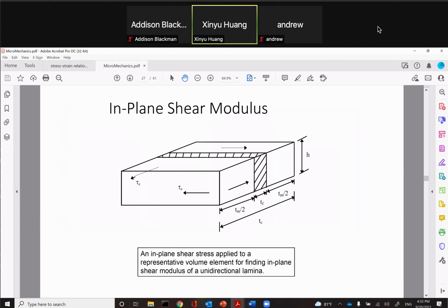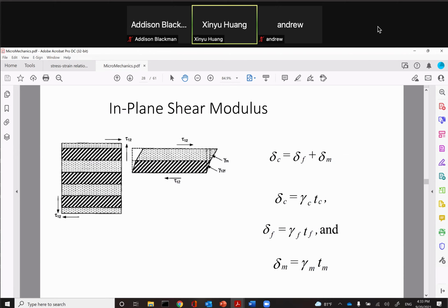In-plane shear modulus. Again, you can basically use an equivalent. You think of this brick of 3 layers, and then you assume this approximately represents the composite behavior. You assume one of the brick layers is matrix, the other 2 are fibers, and then you can apply a load to it and see the response. Okay, so this is the equivalent material, an imaginary material that you invented.